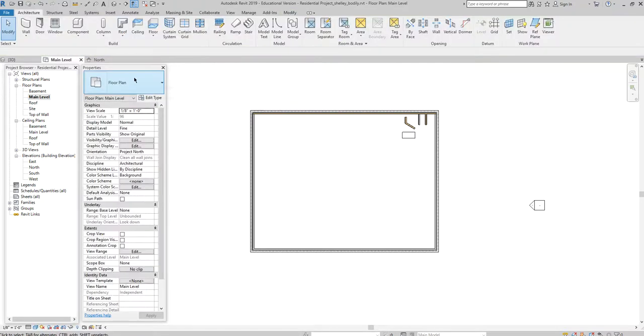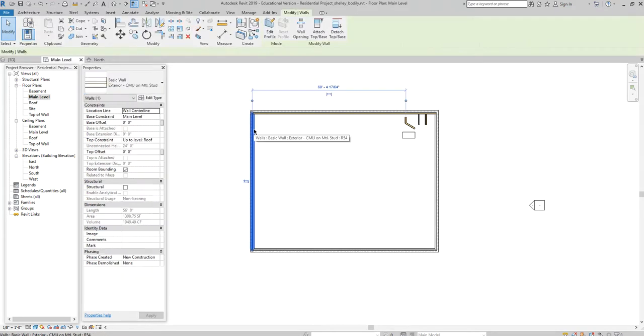It's a pretty important thing to recognize because when you are in Revit and you want to create new walls and there's a wall type that does not exist, within Revit we don't have a button that says, click here for a new wall type, click here for a new window type, click here for a new door type. We don't have a new type button. The way that Revit works is you take an existing object and, when you're creating a new wall type, for example, you choose the wall that is most similar in assembly to the new one that you want to generate. You're going to duplicate it, rename it, redefine it, and then reuse it.